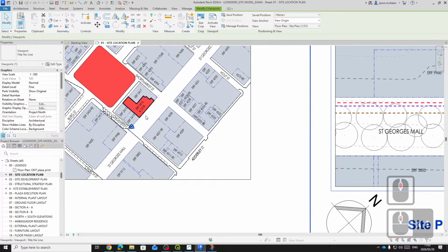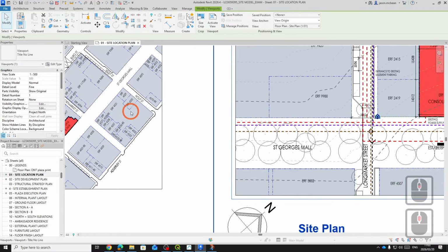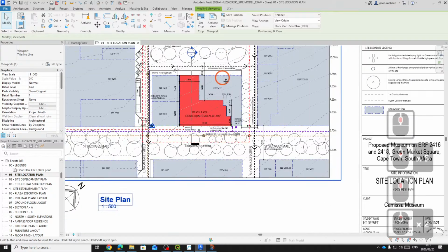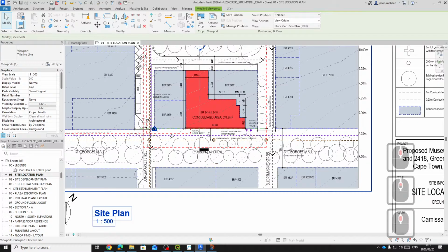Okay, it doesn't have a lot of information on, it just has a bit of earth boundaries and street networks. You don't have to put trees and all of that information on. Now, when you start putting your site plan together, you first start documenting the existing contours, the existing roads, and that's where you use an aerial image. You drop that in, scale it. You guys have done this last year to a degree, but then you start documenting the existing trees.